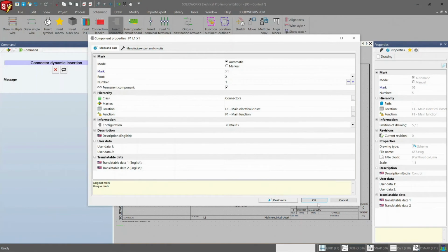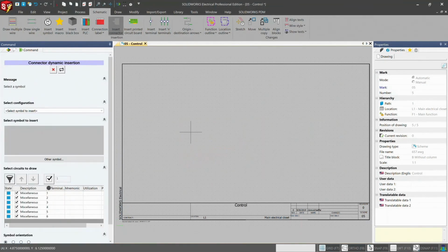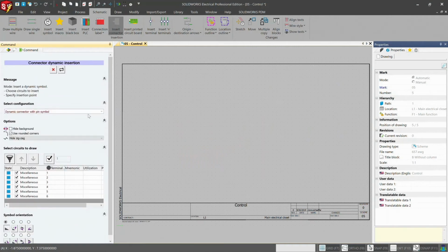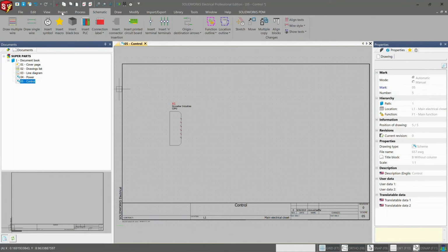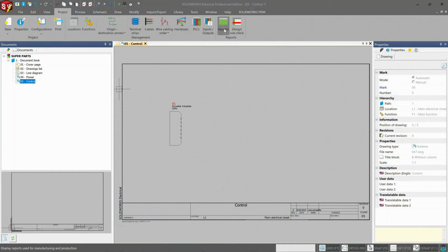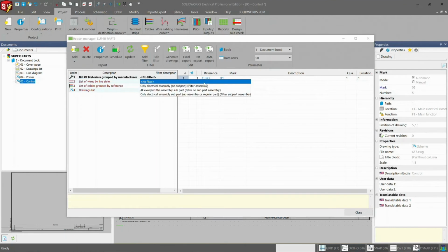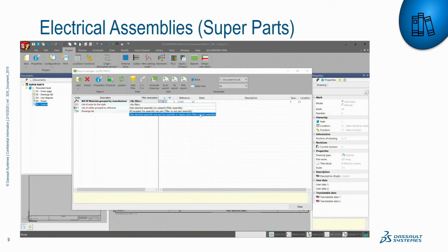Now, these are incredibly helpful for times where you have a repetitive part that you need to add that has many different parts to it. And it can also be something that you add throughout your entire ecosystem. So you see here I have added it, and I have it in my bill of materials. And something new coming down, I can either show it as one individual part, or I can show it as all the parts broken apart as their own individual elements.